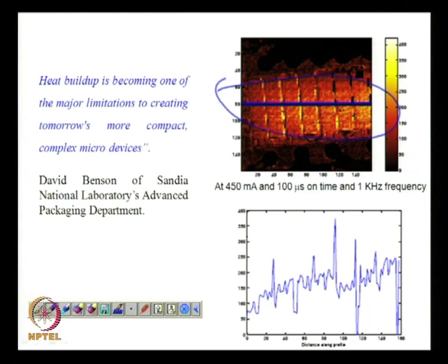Now, if you think of this as the chip, then while designing such a chip, you have to make sure where exactly you are going to put the heat generating components. All the components are not going to generate heat all the time, there would be some time gap in between. So, when this one is in operation, the other one may be switched off and so on. So, it is a complex transient problem that one has to look at. Additionally, we are not going to have just one layer or one level of chips. There will be several circuits sandwiched or put on top of each other.